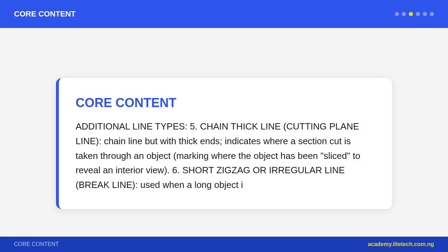30 degree or 60 degree lines: 30 degree, 60 degree, 90 degree set square. 15 degree or 75 degree lines: combination of 45 degree set square plus 30/60 degree set square. Line quality, important rules. Lines must have consistent weight, thickness throughout. Draw with smooth, confident strokes, not short sketchy marks.